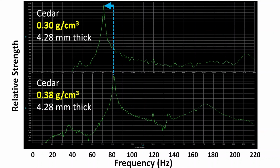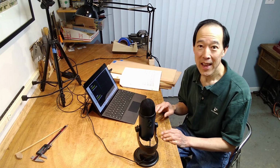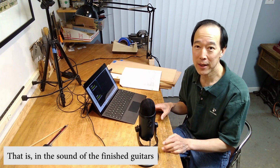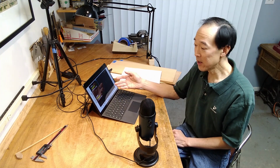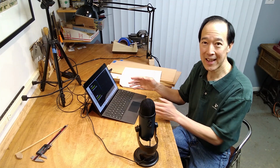And so if we built soundboards with these different materials and we left the thicknesses exactly the same, that would have ramifications on the sound for sure. And one wouldn't necessarily be better than the other, but I can say that the one with the lower density soundboard would have a more bass-oriented sound, whereas the one with the denser soundboard would have the sound slightly shifted to the treble orientation.